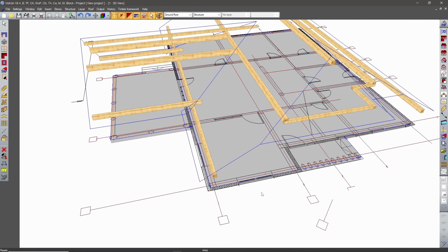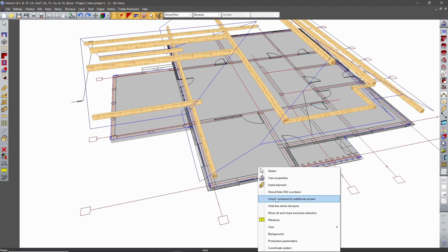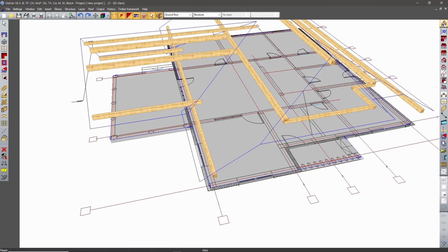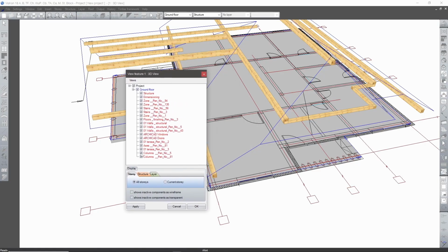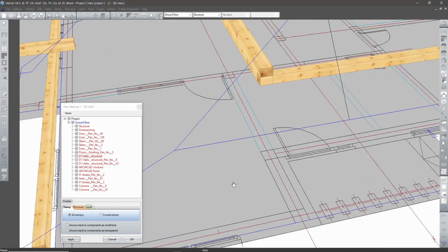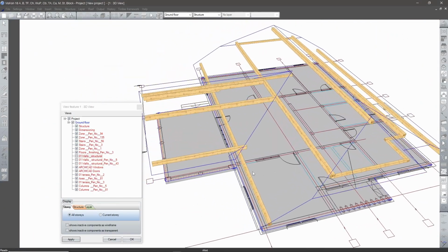And to make point selection easier, you can temporarily hide certain structures. This is where the layer management I mentioned at the beginning becomes very helpful. By clicking this icon, or this one here, you can quickly find and toggle off unwanted elements, like these ones, for example. Hit apply, and now we have a much clearer vision.